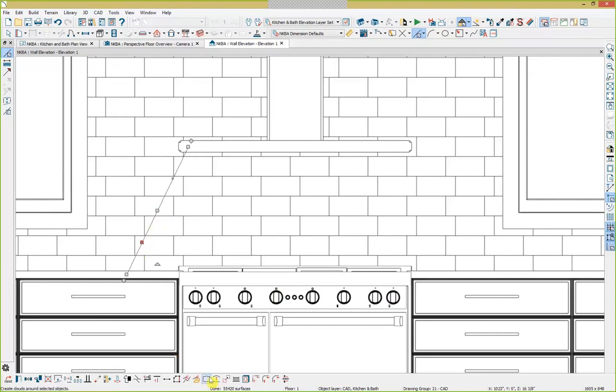So we're going to go ahead and select the curve button in the bottom toolbar. You can see there's a little orange triangle handle that you can use to adjust the curve. You could also open up these independent sections and manually type in a radius if you needed to. So now that we have the one side curved how we would like it, we're going to do what we've already learned in copying and reflecting it to the other side.